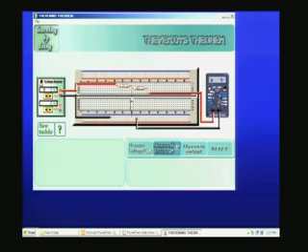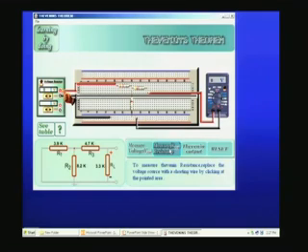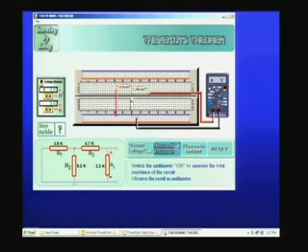We will go ahead to measure the Thevenin's resistance, R Thevenin. We will have to calculate R Thevenin. We know the rule. The rule is replace the power supply with a short. So when I click here, you find this point is connected to the ground by using a shorting wire, and the power supply is disconnected. Now I have only 3 resistors. The RL is removed. Under open circuit condition, I will measure what is the resistance here.